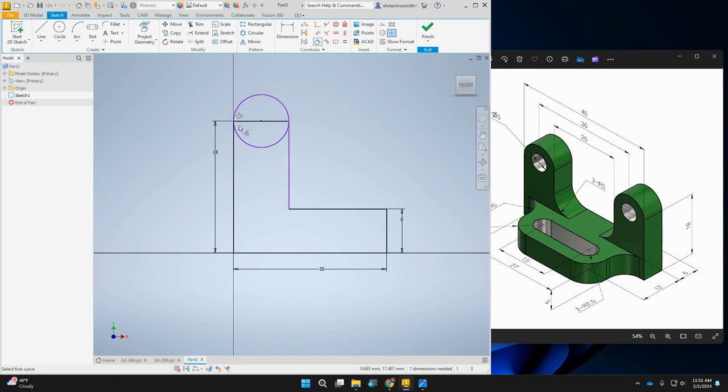Alternatively, if I wanted to not have this bottom part down here, I can create an arc. There's a couple different kinds. There is a tangent arc, but if I did a tangent arc, it wants to know where my starting point is, my ending point is, and see how it's kind of goofy here. So I really like the 3-point arc. We can click here, it goes to there. We can go like this, and then we can use our tangent to bring it in. So a couple different ways we can do it. All of them are going to get us the same result. So we're going to leave it like that.